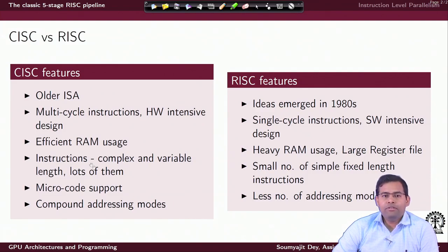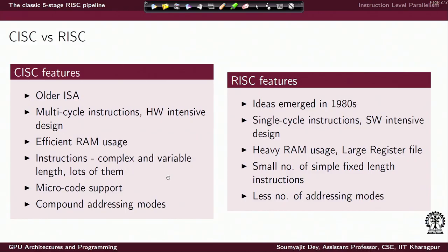Overall, the point is the CISC instructions may vary in length, whereas for RISC, the instructions, all of them are very regular, they are going to be of the same fixed length, because they are quite generic, they are all single cycle, their intensiveness in terms of hardware usage will be kind of similar. So, they will all be of similar, exactly the same opcode length.